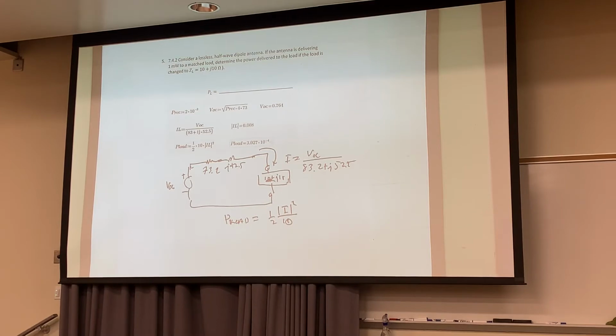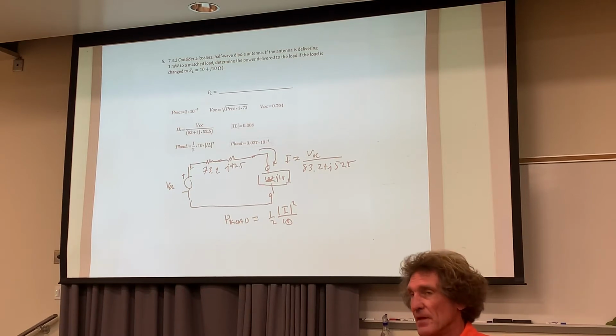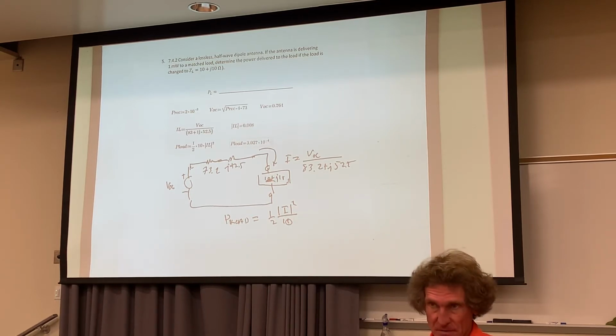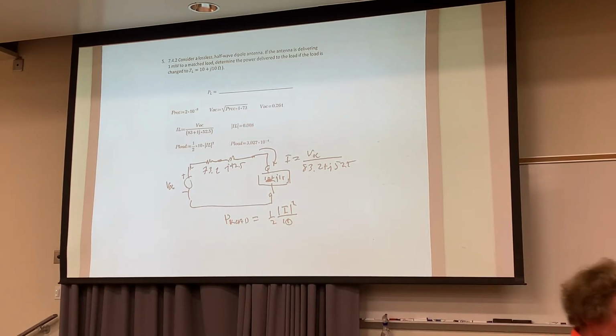The first thing we do is find out what things look like, resistors, inductors, and capacitors at high frequency. How all of a sudden an inductor has a capacitance and resistance associated with it. How a resistor has a capacitance and an inductance, and how a capacitor has an inductance and a resistance. And none of these elements at high frequency look like what they're supposed to. They look much different, and that's the problem when you do high frequency engineering. You have to know, even though you might say 20 picofarads, that lead length might dominate the impedance at the frequency you're using. So you have to make adjustments. You have to do all sorts of things.